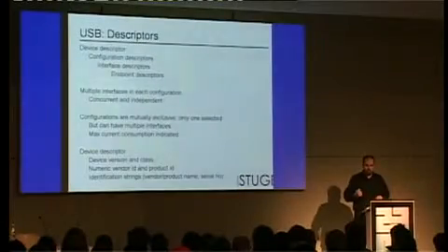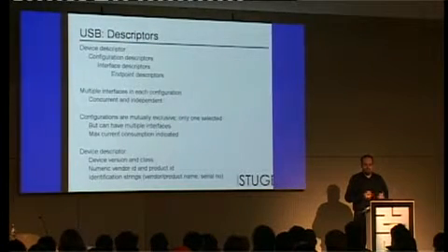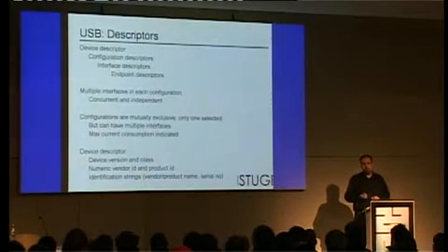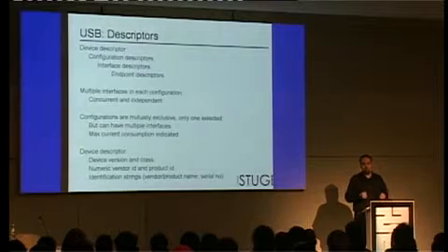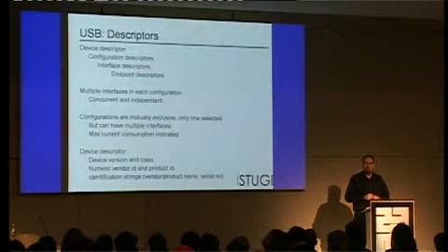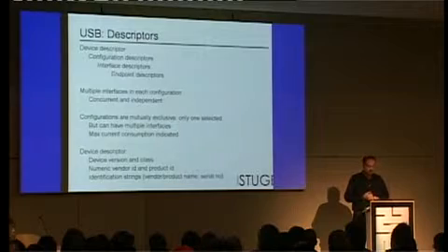They're not using either configurations or interfaces. They're using their own vendor-specific thing to switch the personality of the device completely. So even though they could use these two configurations, they decided to make their device appear as only one thing at a time. When you first connect it, it's a CD, and if you send it some magic thing, it's going to disappear. It's going to disconnect from USB and then switch something internally, and when it comes back, it's all of a sudden a modem. Does that answer your question? Yes. Thanks.